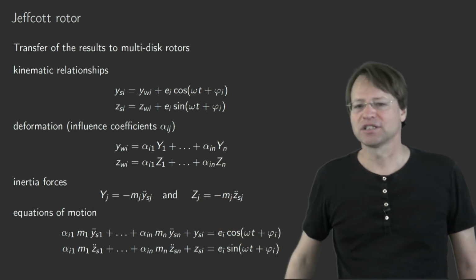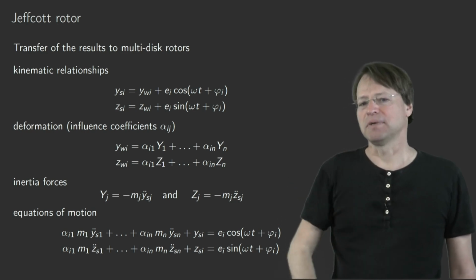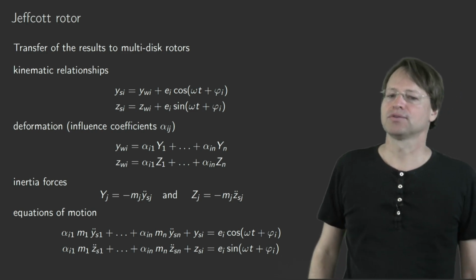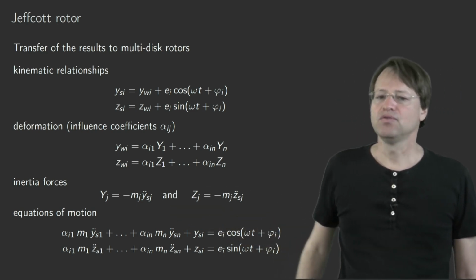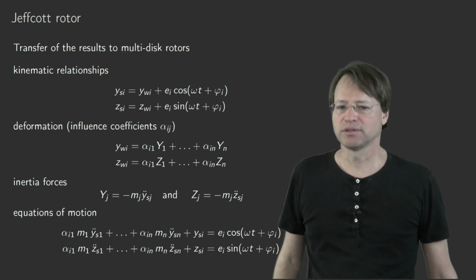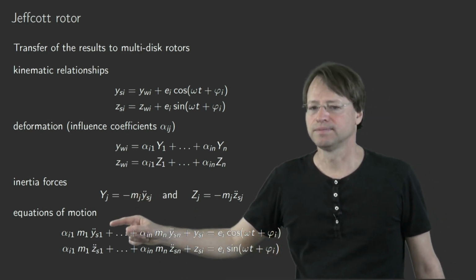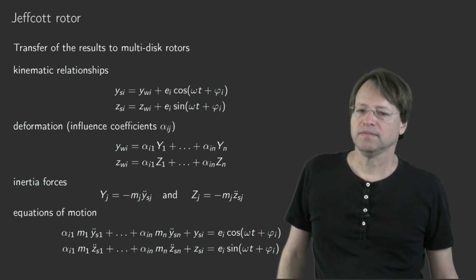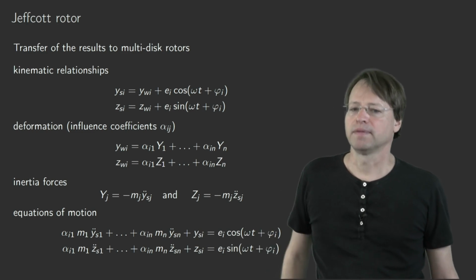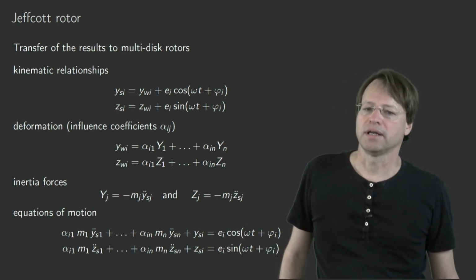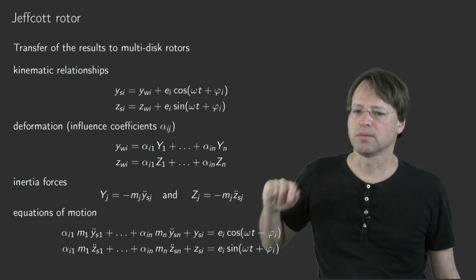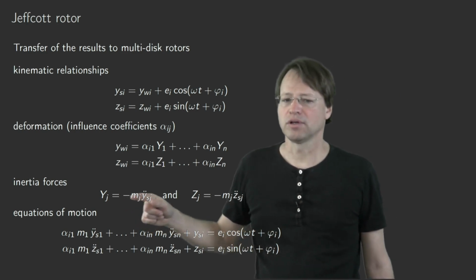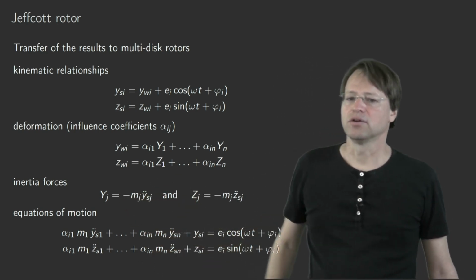The kinematic relationship plus the deformation described by influence coefficients plus the plug-in of the inertia forces, and at the very end you will end with an expression that includes the inertia forces for the coordinates y sub s and so on, for y sub 1 until y sub n. So these are the contributions from the inertia forces.